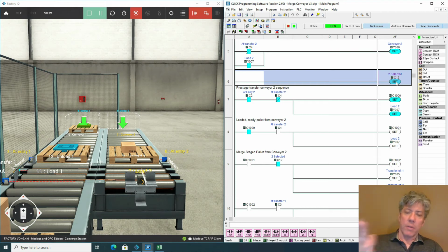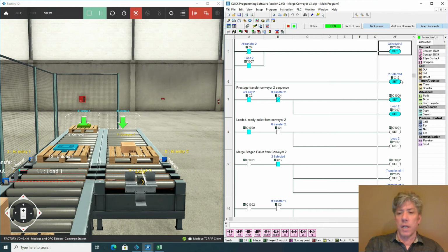Now, with set and reset, it's harder to avoid. A lot of times there's other logic where one portion of the program needs to turn a bit on, maybe some other portion of the code needs to be able to turn it on in other situations. But you see this problem more often with just output instructions themselves, where students will figure, well, here's the logic for turning it on and off, and write that in 1 rung, that's done. And later on, they need to turn that particular thing on or off, and they write another rung that overwrites what their previous rung had done. Basically, it's a new calculation. If I tell you, okay, x equals 3, and then tomorrow I'll tell you x equals 4, and I say, what does x equal? Well, I've overwritten the value of x, haven't I?